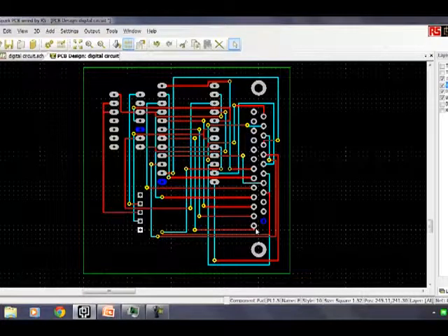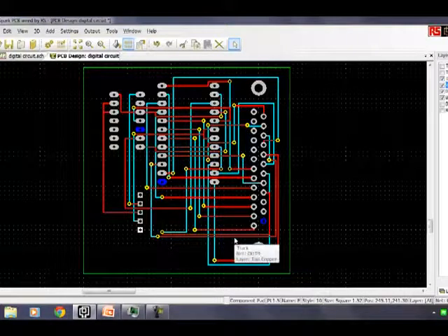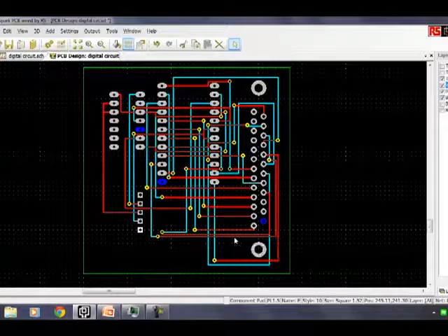EMC issues, where we may want some protection. All in all, using the translate to PCB function, which you saw within the wizard, makes it a little bit easier: you can automatically insert new layers and assign them to whichever nets you see fit. In the case of today's example, we used the VCC and ground nets to do that.